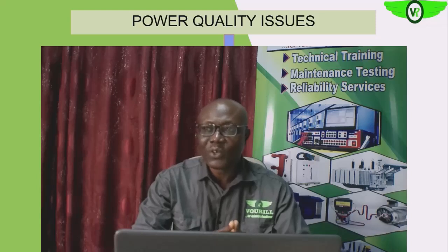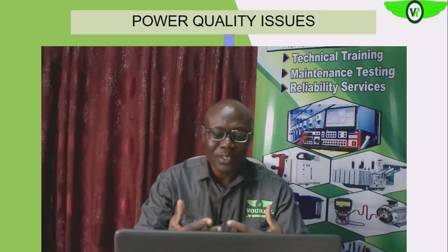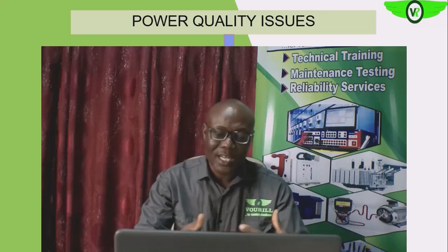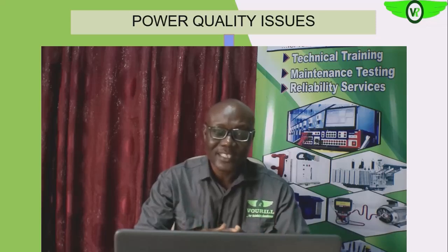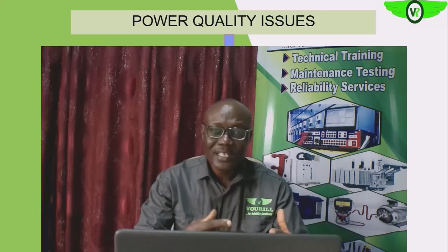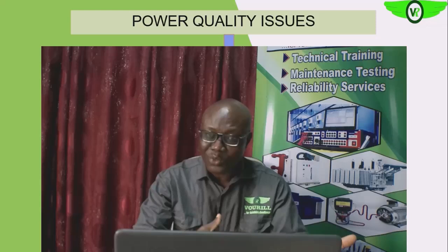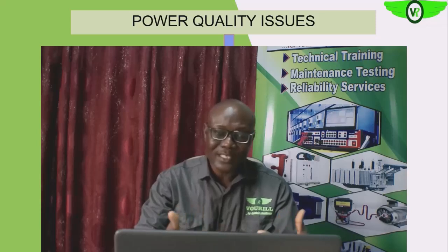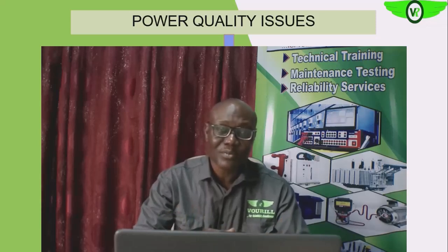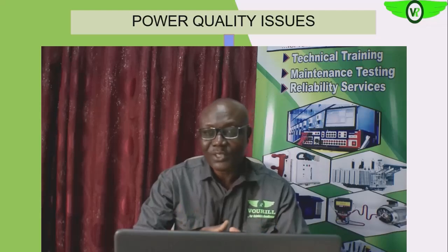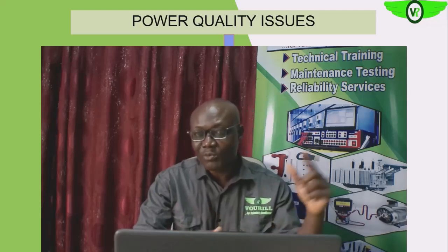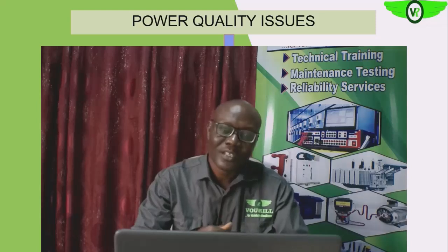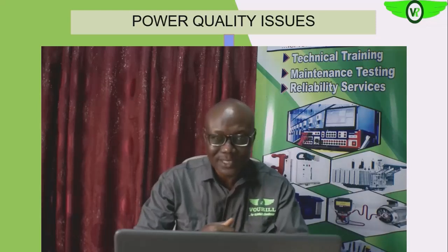It's not good for our system because it has the tendency of increasing the losses also. You see that the motor will tend to want to run at a higher speed because of that increased voltage level, which may not be good for the end products in our system.